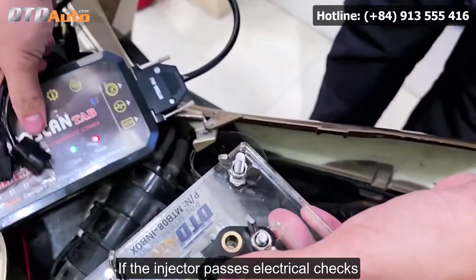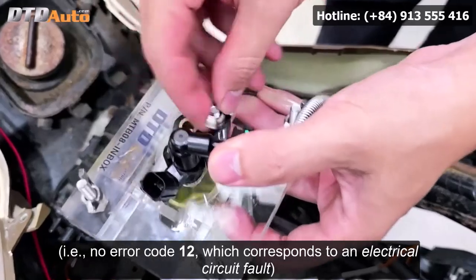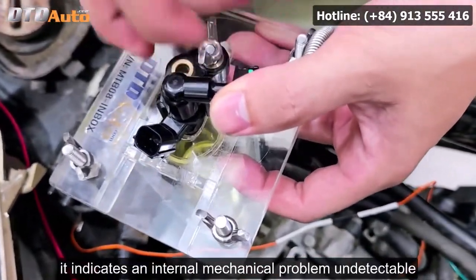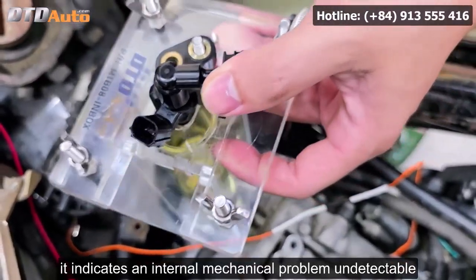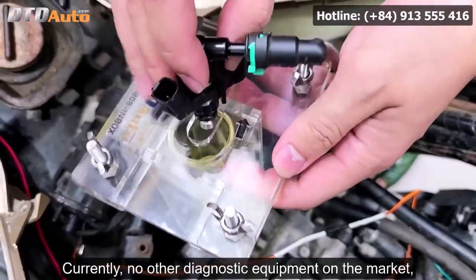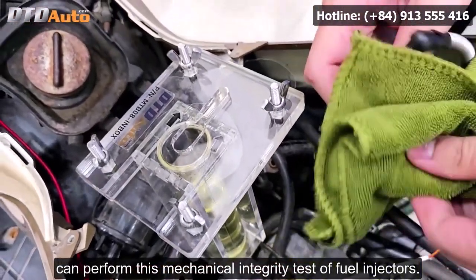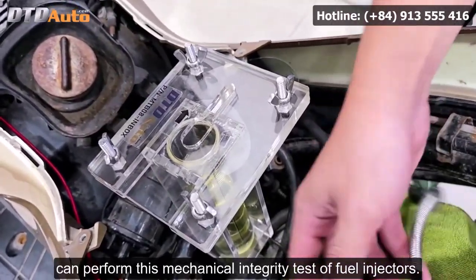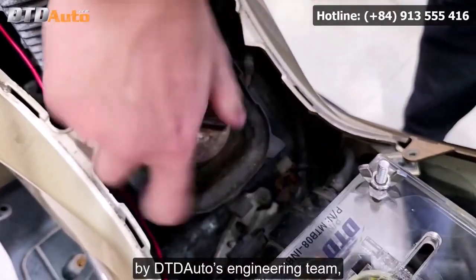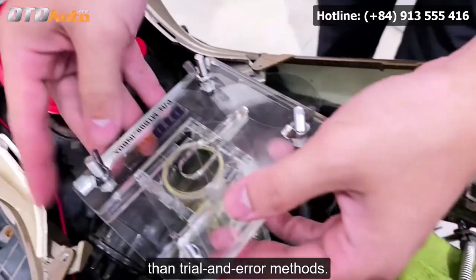If the injector passes electrical checks, i.e. no error code 12, which corresponds to an electrical circuit fault, but fails this mechanical test, it indicates an internal mechanical problem undetectable by standard diagnostic tools. Currently, no other diagnostic equipment on the market, except MOTOSCAN tab, can perform this mechanical integrity test of fuel injectors. This feature represents a pioneering advancement by DTD Auto's engineering team, achieved through rigorous scientific research rather than trial and error methods.